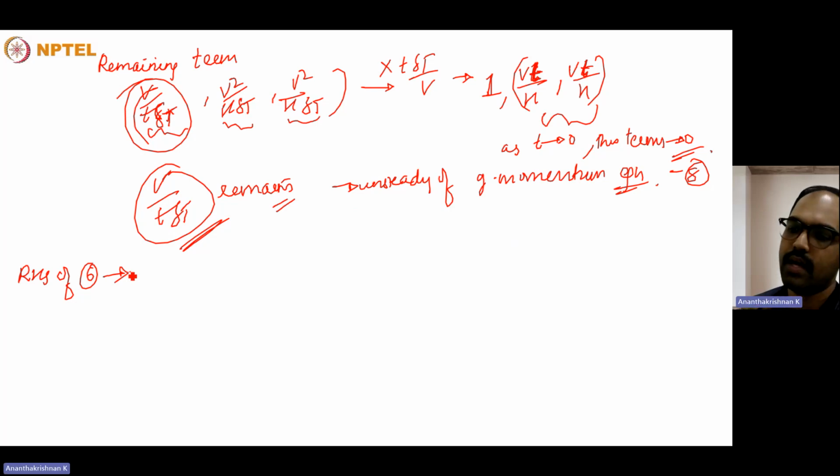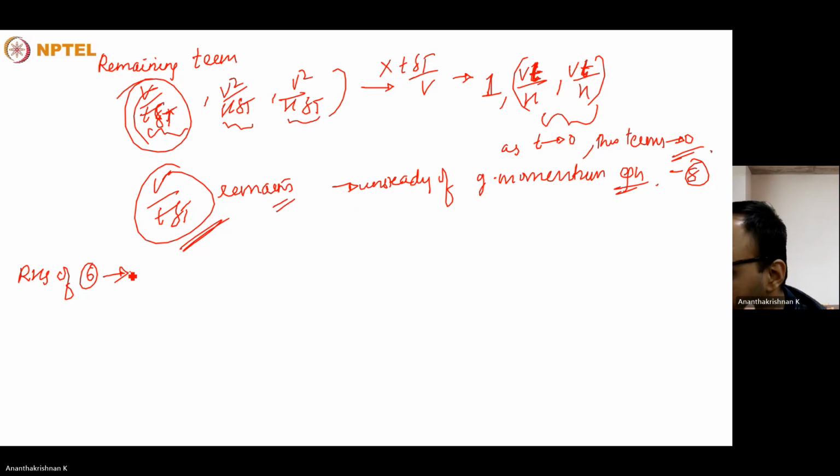So we have actually got an issue here, because in the case of natural convection, since the continuity equation is there, we have three equations. So we combined the x and y momentum equations to remove pressure.